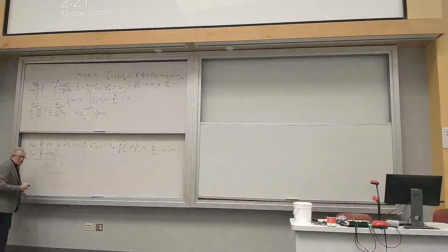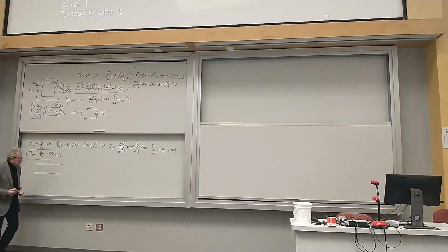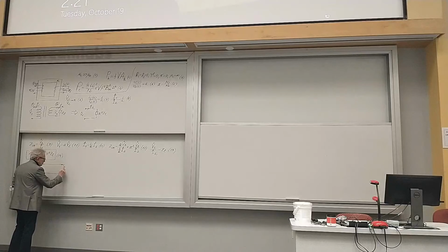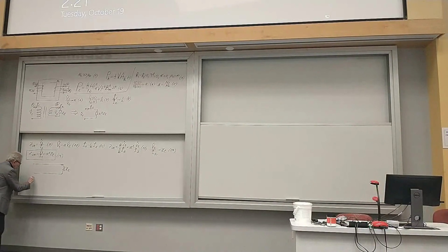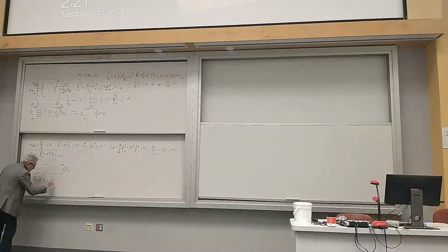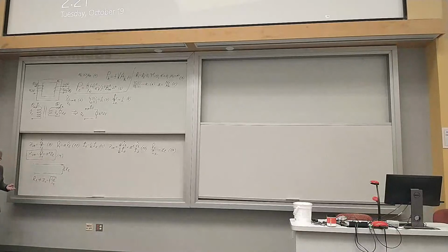But anyway, so this is the transmission line, and you will put here some load. First I will consider a resistive load. And this arbitrary resistive load is not equal to the characteristic impedance. In general, it's not equal to the characteristic impedance of the transmission line, which is given by this formula. If you neglect the small resistivity of wires, it's equal to the ratio of inductance per unit length, L sub 0, to the capacitance per unit length, C sub 0.